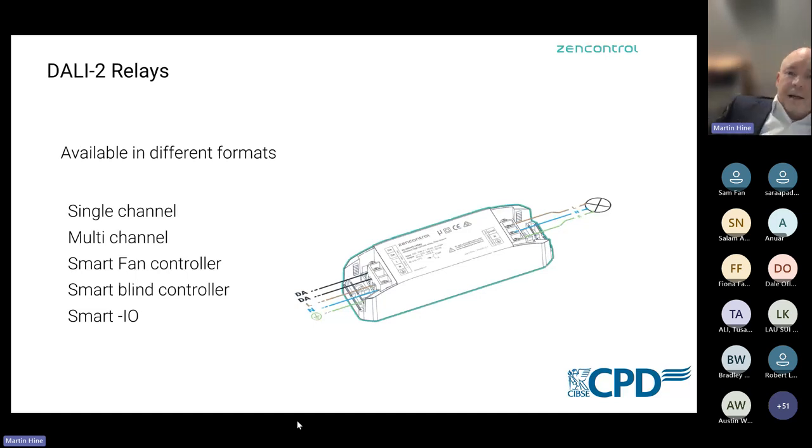So most applications, as I say, with BREEAM, the lighting control tends to take control of the water solenoids. As someone enters a room, the sensors identify presence, and then they can switch the relevant solenoids on and off.